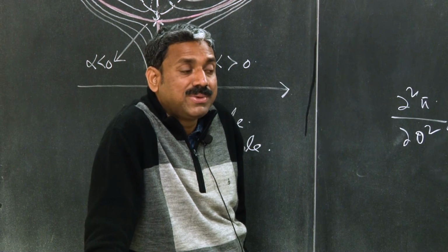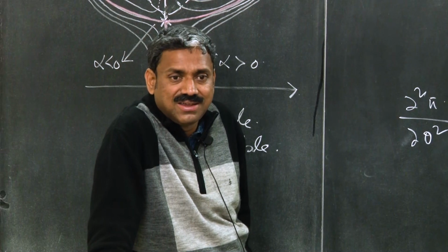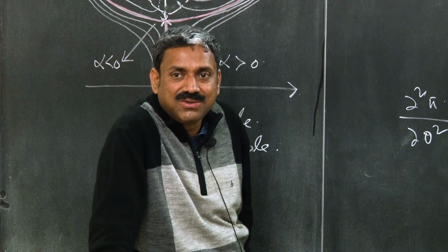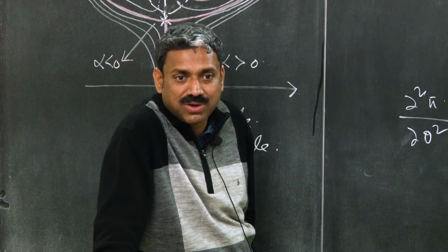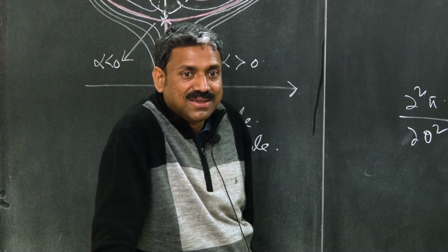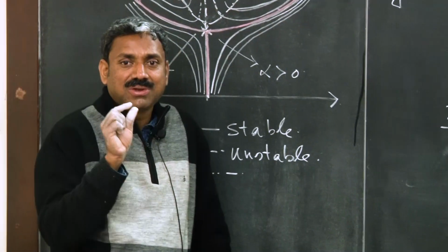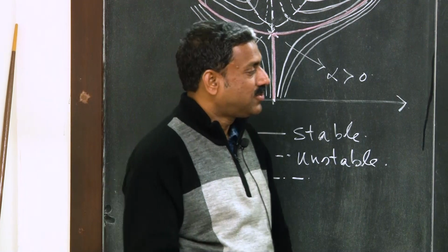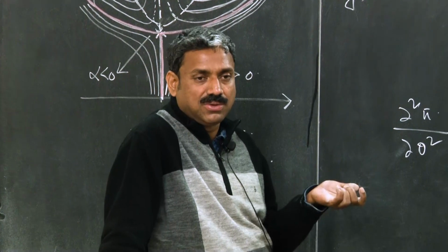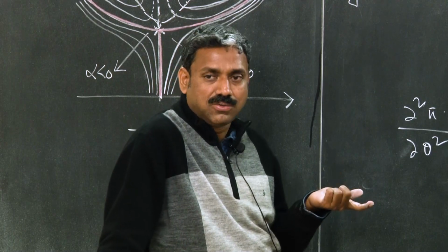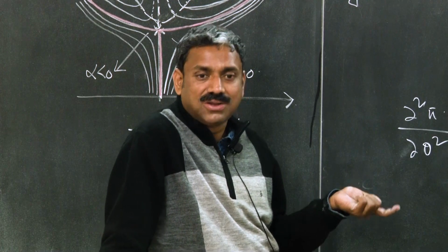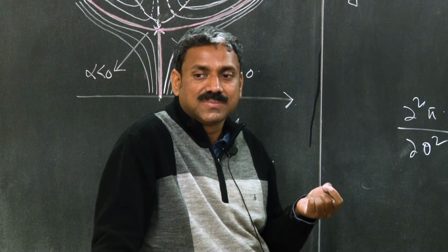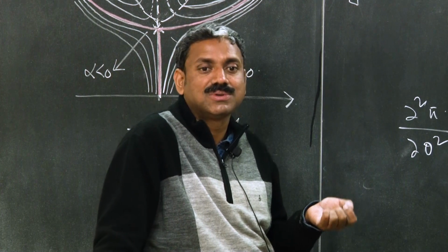You don't write the equilibrium directly, you write the equilibrium in the incremental form, right. So instead of potential energy minimization, you take the incremental potential, delta pi is equal to 0, right. So you write down the equilibrium in incremental form, okay. Then what does the incremental form lead to? You can write the same incremental form in two different ways. One is energy, but in nonlinear finite element it is easier and more convenient to use virtual work, because the virtual work equation is more generalized.